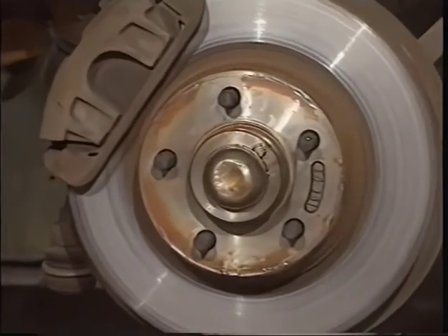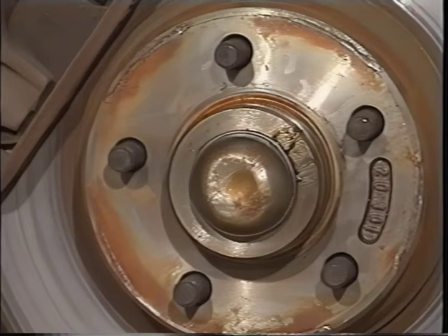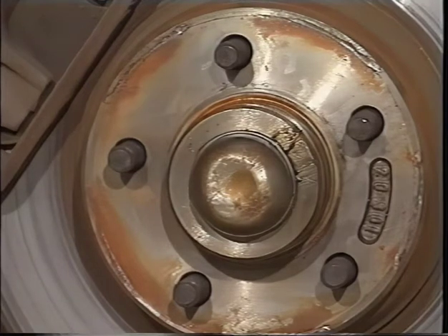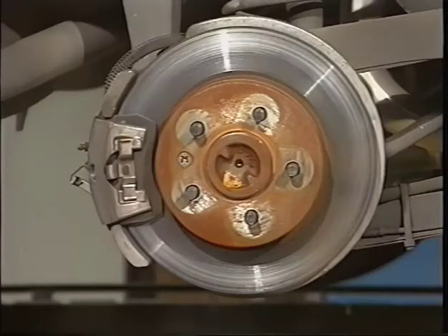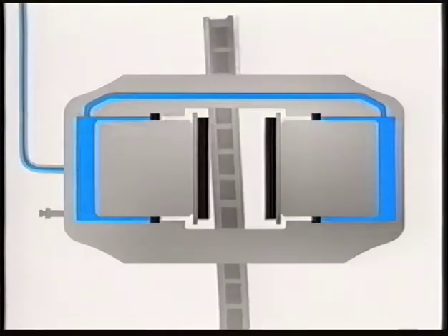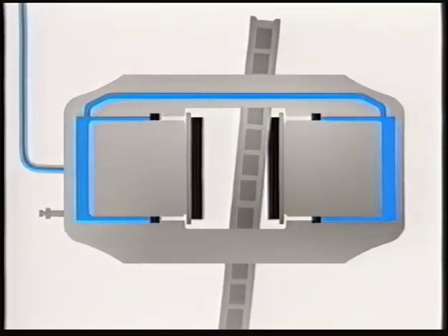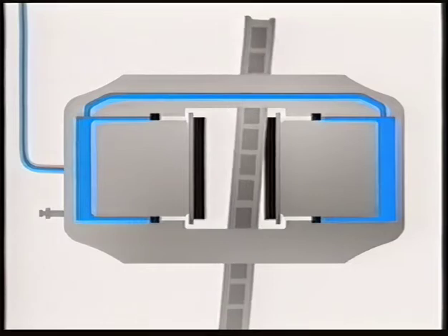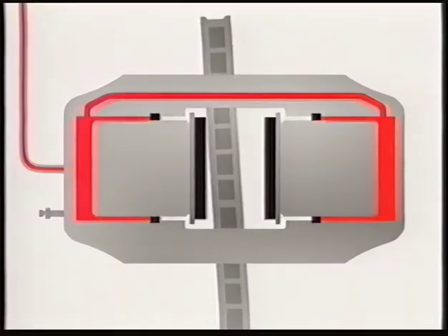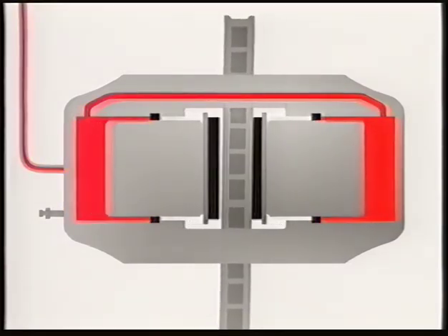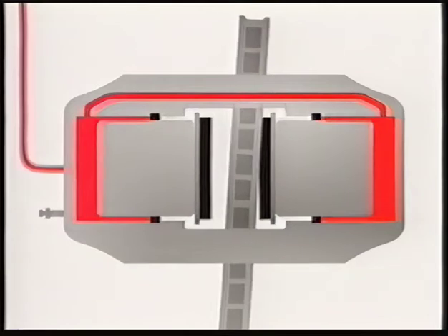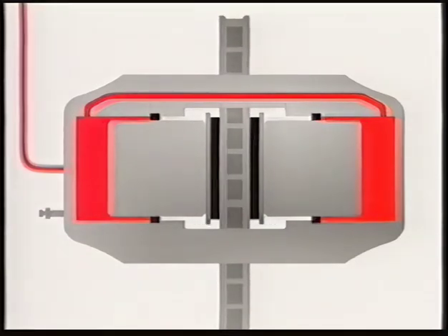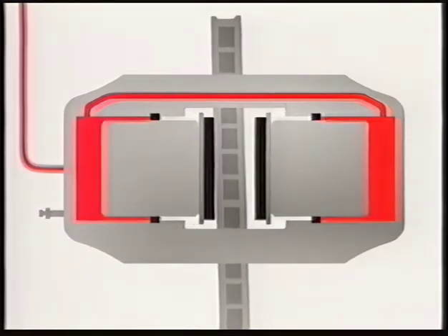Loose wheel bearings, the second problem associated with disc brakes, causes pad knockback and occurs when either front or rear wheel bearings have too much free play. This allows the disc to move an excessive amount laterally, pushing the pads and pistons away from the disc. Again, we are faced with increased travel to bring the pads into full contact with the disc, and again, the master cylinder must displace more fluid.